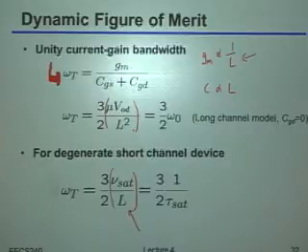Can we think of it as the frequency we can operate at safely? To the extent that it's related to omega t, and we'll say more about this later on, omega t really tells you, relative to the gain bandwidth of your circuit, how much the parasitics from your own transistor are going to impact how much power you have to dissipate, and whether or not you can even hit that bandwidth in the first place.